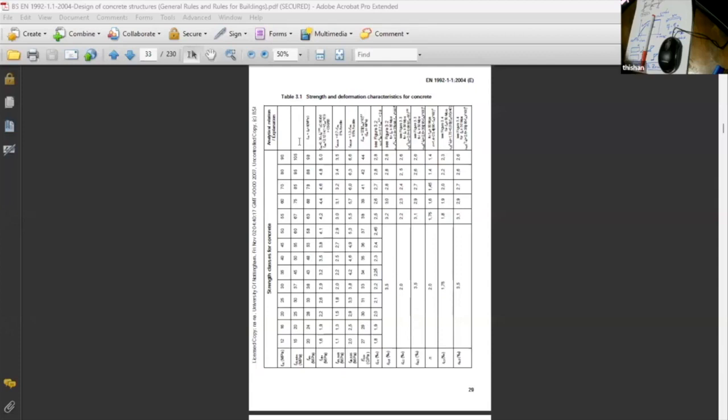So if you take a pile like 1.1 meter, 1.2 diameter, do maintained load test. Then do PDA on the same pile. What can we do? We can calibrate the PDA results for that particular site rather than using data from other sites. Right?